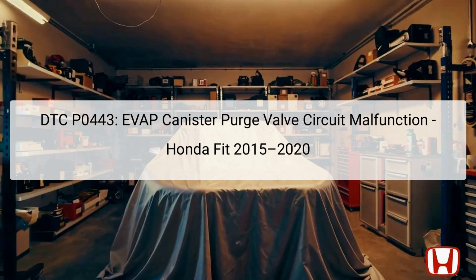The EVAP system is designed to prevent fuel vapors from escaping into the atmosphere, and the purge valve allows these vapors to enter the engine during certain conditions. The valve is located in the engine compartment, connected to a vacuum hose serving the fuel system. When this valve malfunctions, it might either remain stuck open, allowing excess fuel vapors to flow, or remain stuck closed, causing a buildup in pressure. Understanding and resolving this DTC is essential to ensure the vehicle operates efficiently and meets emission standards.